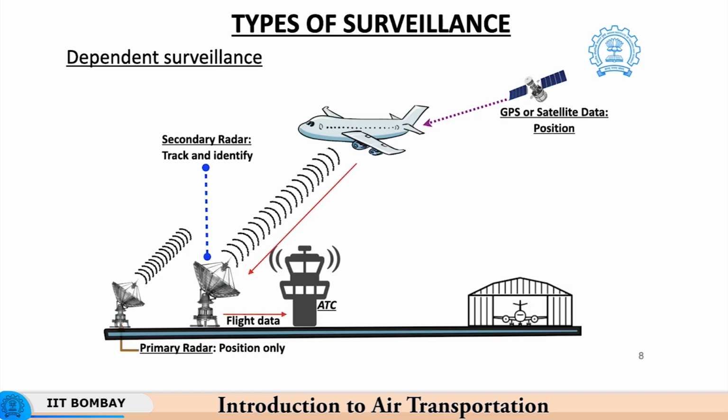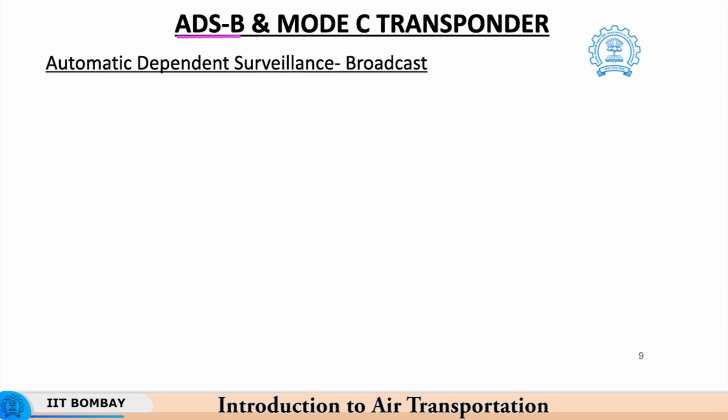Subsequently, this data is provided to the nearest ATC, and also through the usage of a special data link communication protocol called ACARS, the particular data is transmitted to the airport ground control station also. More details related to ACARS will be provided in a later part of this presentation.